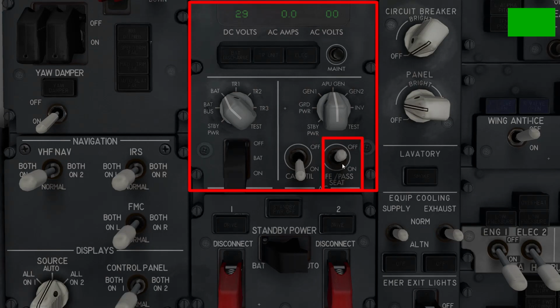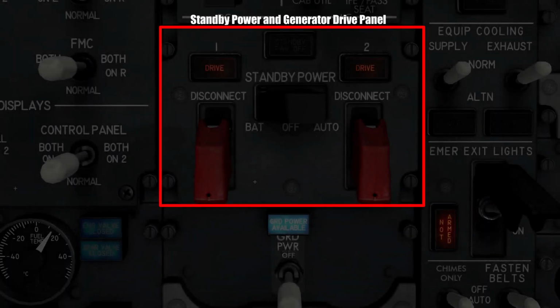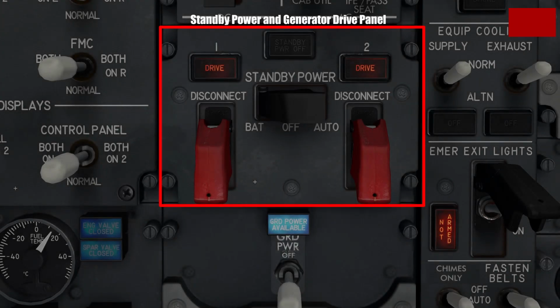The switch on the right, labeled IFE/pass seat, stands for in-flight entertainment or passenger seat power, which enables passengers to use electricity to access the in-flight entertainment systems, as well as use power supplies to charge their own personal devices for airlines that support these. Moving below, we have the standby power and generator drive panel.